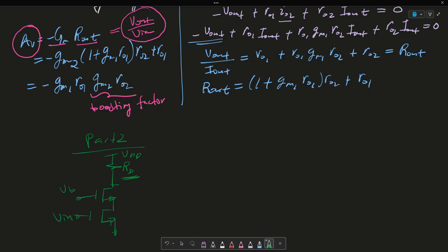And for part 3, I'm going to do the same thing, but with PMOSes as my current source, in place of my current source. So these are all V biased, and V biased just means a DC voltage source. All right. So please look out for those 2 parts coming up.